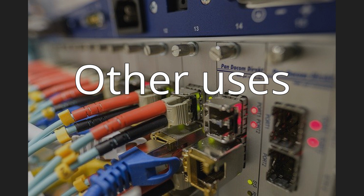An optical fiber doped with certain rare earth elements such as erbium can be used as the gain medium of a laser or optical amplifier. Rare earth-doped optical fibers can be used to provide signal amplification by splicing a short section of doped fiber into a regular undoped optical fiber line. The doped fiber is optically pumped with a second laser wavelength. Both wavelengths of light are transmitted through the doped fiber, which transfers energy from the second pump wavelength. The process that causes the amplification is stimulated emission.